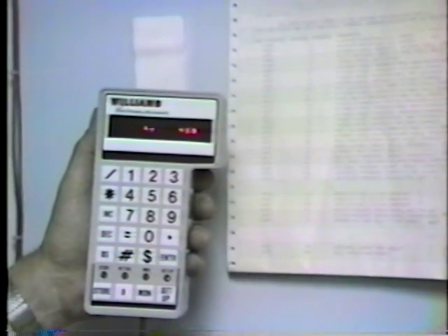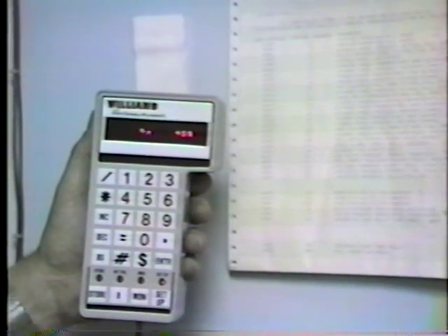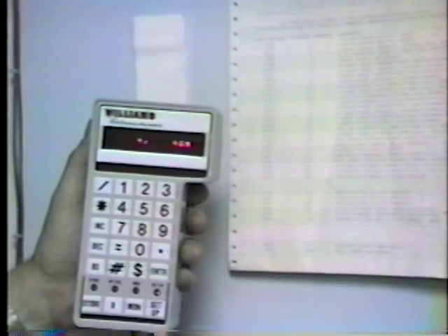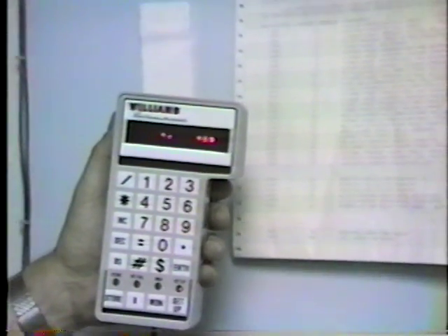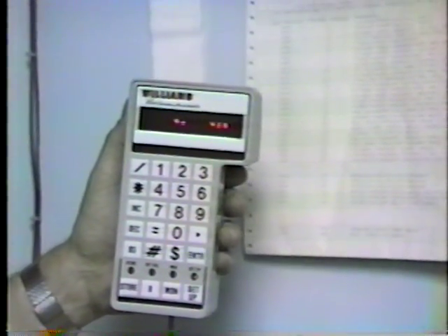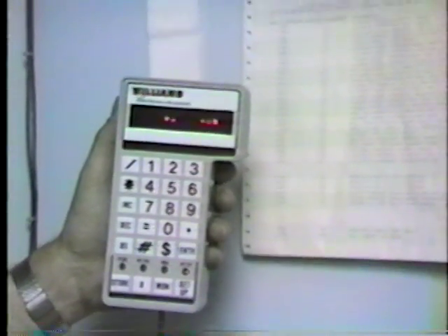In other words, this reads as a percent of the scale. And the scale is a 0 to 15-inch scale, so you would take 46% of 15. That's correct. And that would be the set point.